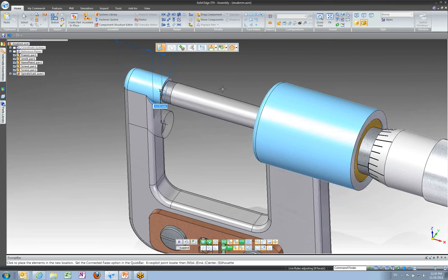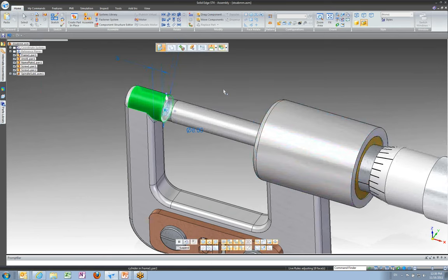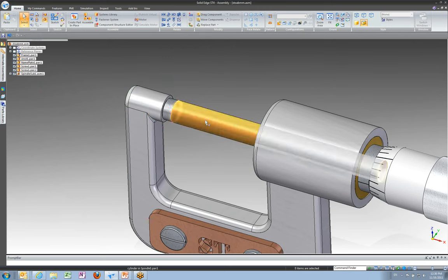So at this point, I just want to kind of move up from where I originally am, and you can see my original position is kind of in gray there. So I want to move up from that and then key in 6 millimeters because that's my new offset. And it will go and modify the part, keeping my design intent. It's precisely modified that to be 6 millimeters higher, and my assembly relationships have carried on the adjacent parts along for the ride.